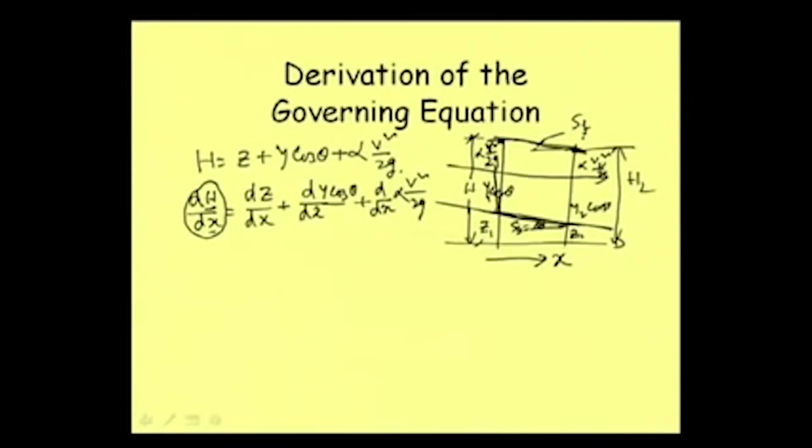And as head is falling in this direction, because energy here is more, we are writing this as minus SF. Well, if we want to give the value of SF, then the numerical value of SF we need to give positive, because in the equation we are using the negative sign to indicate that it is falling. So, in the equation itself we are using this sign concept, and the numerical value we calculate for SF should be positive, because we are already assigning the sign considering the direction.